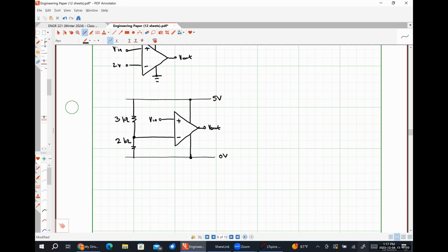2 kilo-ohm here. Another reason we typically use kilo-ohm size resistors is to remind us that the output resistance of an op-amp is usually on the order of tens of ohms to hundreds of ohms. So we need something larger than that output resistance so that there's not an appreciable voltage drop over the internal output resistance of the op-amp. So the kilo-ohm size resistors is kind of the sweet spot for biasing any practical op-amp circuit. So in this class, you will never see me use anything other than kilo-ohm scale resistors for any of the biasing because that's what we do in practice.